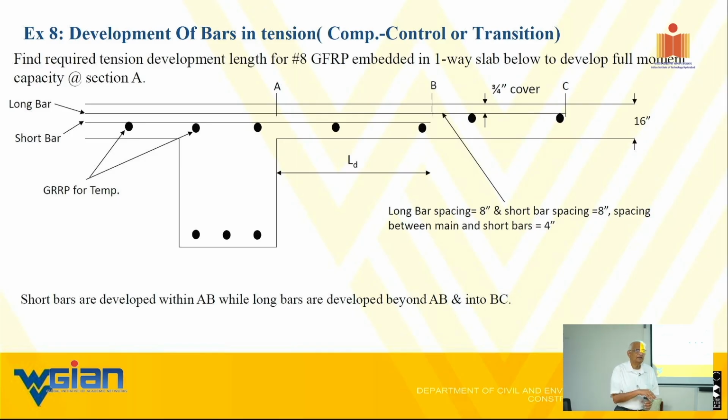So it will increase by 7, 8, 10 times more. That is the definition of confinement. So if you can confine a concrete, even a little bit, why do you think the spiral reinforcement by itself, or even better yet, you confine the columns with FRP composite fabrics?